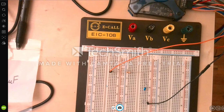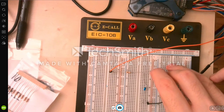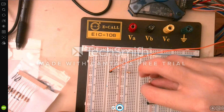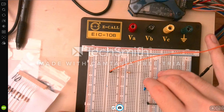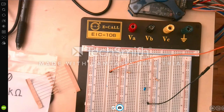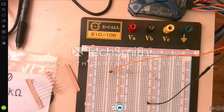Let me take it. Let's put it here. And of course, we need to change the current capacitor with the 0.02 microfarad capacitors. So let's unplug this as well.